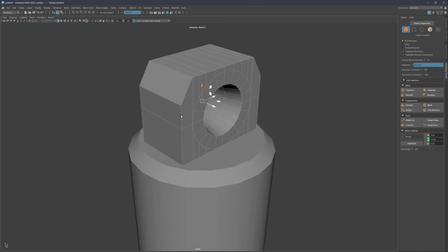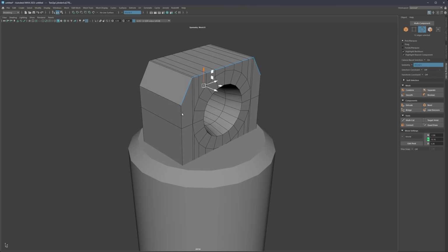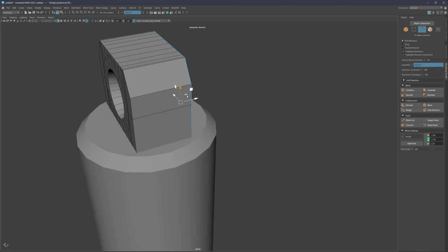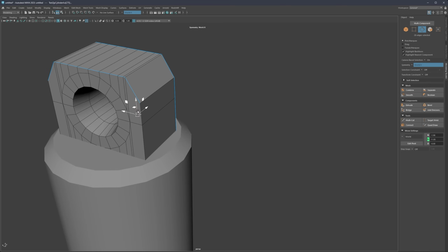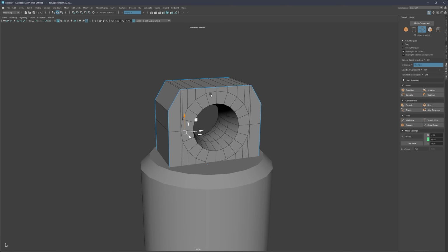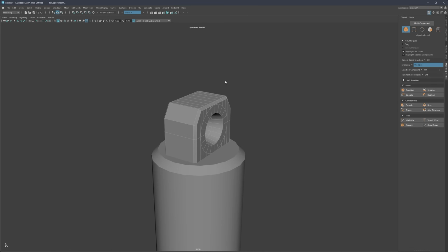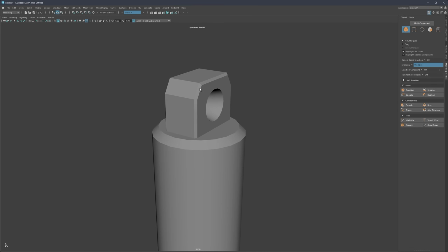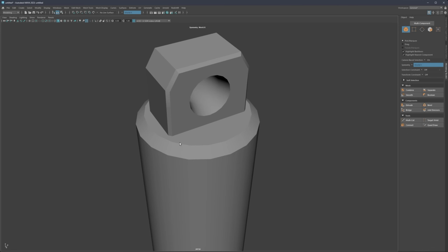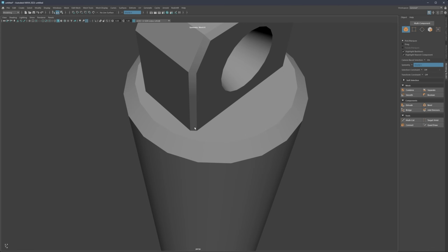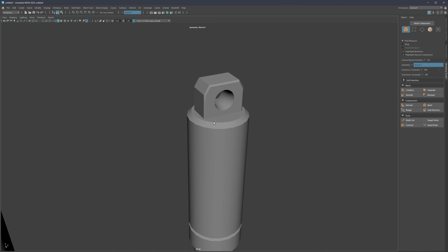And especially, for example, if we decide to create, let me again double click here for the edge, hold Shift, double click here for the edge. And again, holding Shift, just continue double clicking on the edge. And then let's use bevel. Bevel is right here. And let's create more of a bevel. Go to object mode or hit Q to confirm. So let's say if I want to have even more of a bevel, then I just simply need to be careful what kind of topology I'm adding here later down the line.